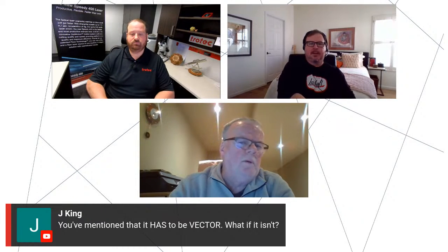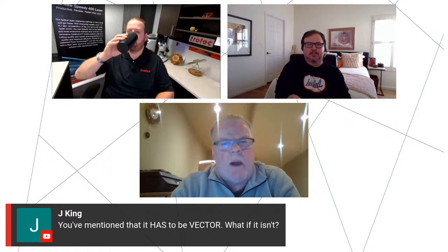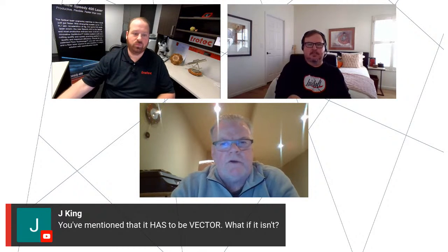Yeah, go ahead, Raj. Sorry, one more thing you can do with that, and I can show you on screen if you'd like. If you do have a raster image, simply use PowerTRACE to convert that to vector. When you're doing the trace, drop it down to 2 or 3 colors. Then you want to keep your original image intact. Once the trace is completed, you can create the boundary, then delete your vector object, and you'll be left with the raster image with the cut line around it.